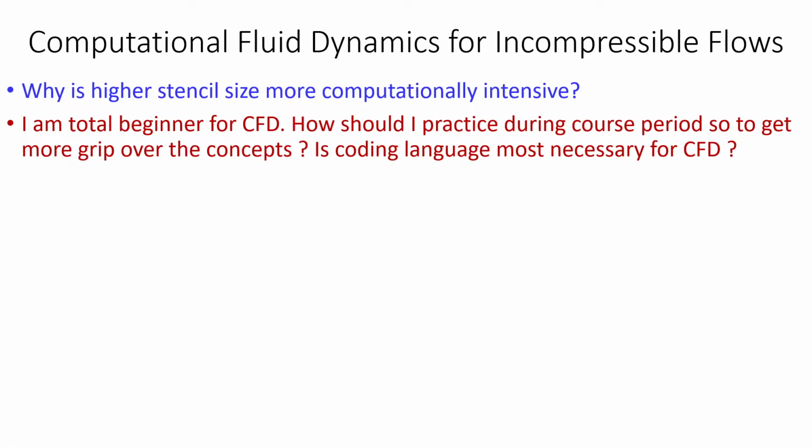So we have received a few questions. These are the two questions related to this course content that I will discuss. The first question is, why is higher stencil size more computationally intensive? If you use a higher stencil size, that means you are using more points which are unknown.